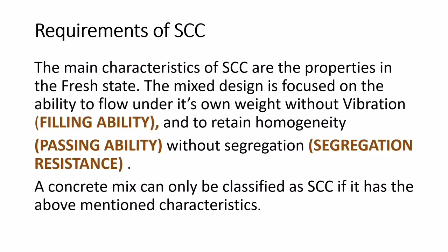Requirements of SCC: the main characteristics of SCC are its properties in the fresh state. The mix design is focused on the ability to flow under its own weight without vibration, that is filling ability, and to retain homogeneity, with passing ability and segregation resistance. A concrete mix can only be classified as SCC if it has the above mentioned characteristics.